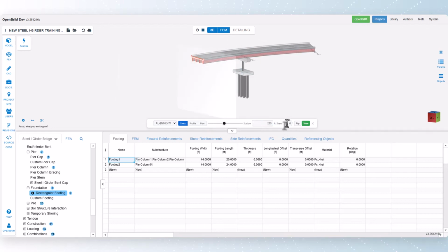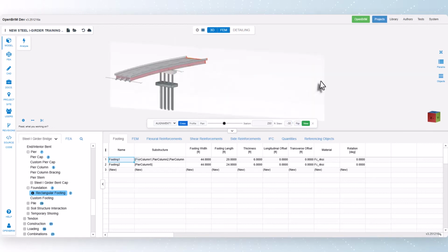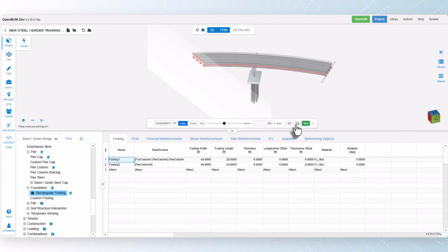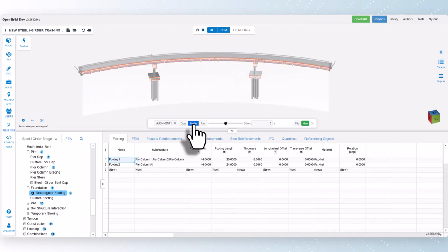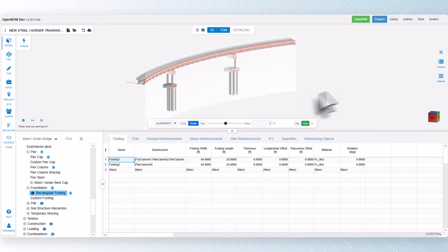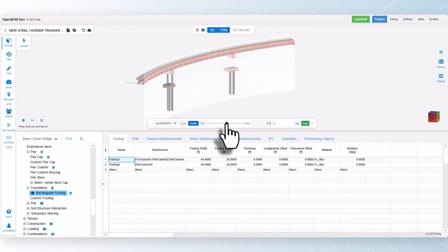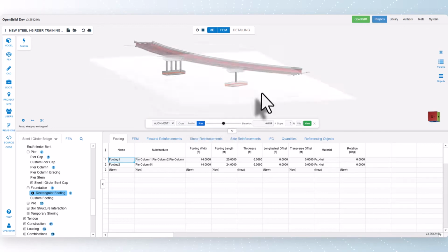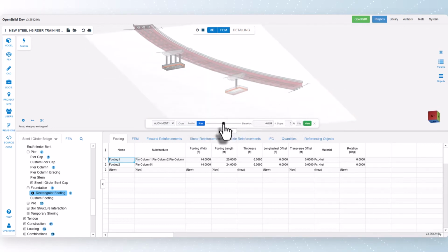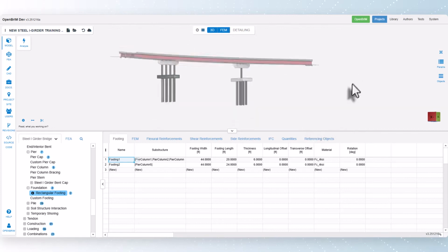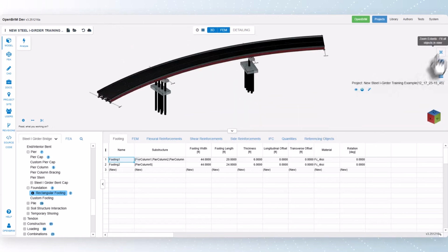You can adjust Skew to angle the section and use Flip to reverse the cut direction. Try Profile and adjust Offset to move the section. And try Plan and adjust Elevation to shift the cut vertically. When you're done, click the X to close the cutting plane panel and exit the tool.